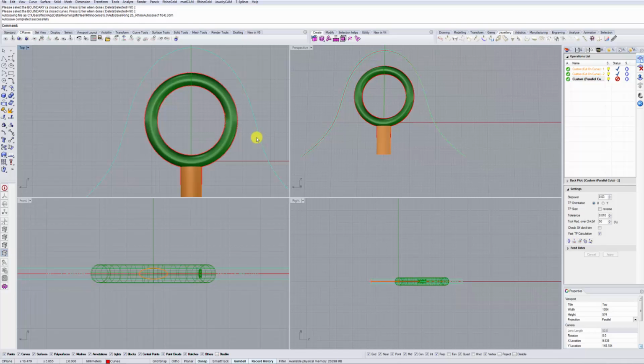It kind of depends on your preference, although there's a catch. If you're going to be cutting using the X direction, like so, you have to make sure that the toolpath starts here and ends here, so that you have the most support on this area. This is the general principle of milling, where you're always trying to mill from the furthest point of your support to the closest. If you're cutting using Y, using this movement, then it does not matter because you're applying equal pressure across the piece. So let me show you the difference here.